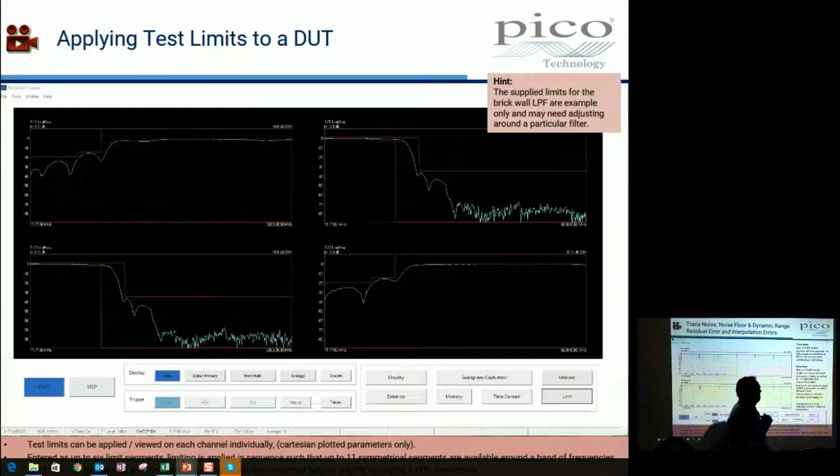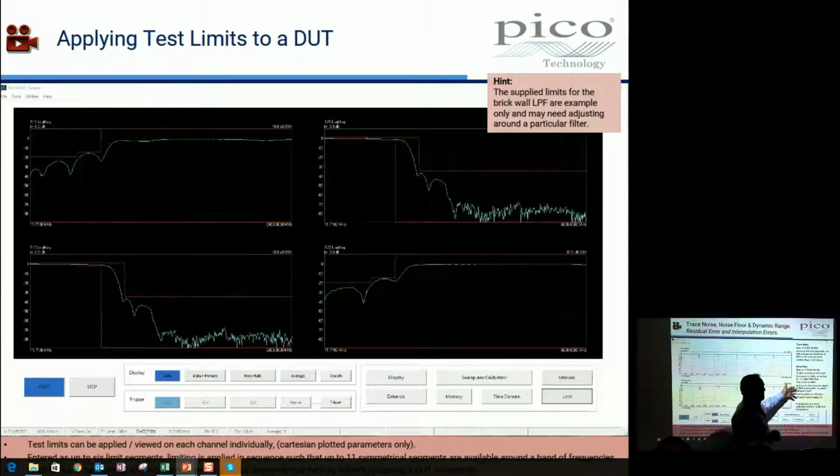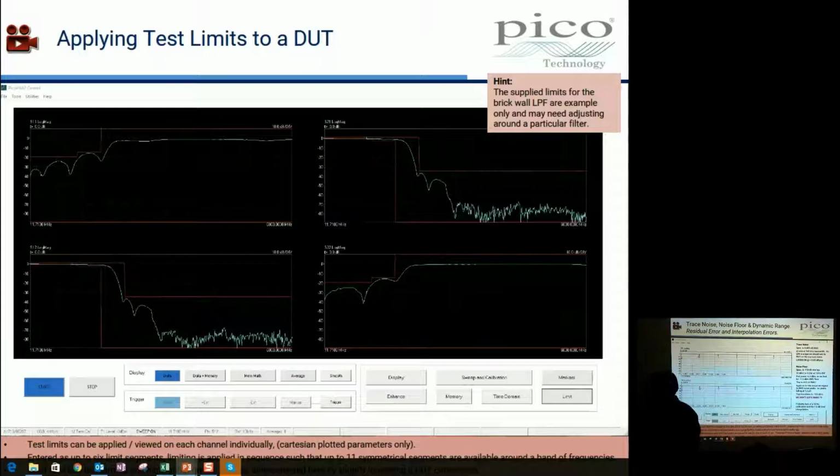Port power is 3 dBm. In the case of the test I'm going to do here, port power is 3 dBm. So we're going to be looking at minus 115 dBm RMS for our noise floor. That's what the spec says it should be. And that is 400 nanovolts RMS. That's pretty small, especially as we're looking at 4 gigahertz signals. We're expecting 3 times RMS noise peaks, so the peaks are going to be falling at around 1.2 microvolts, which translates to minus 105. As you'll see in this demo, we don't quite make it, but then we'll show you how to make it. But let's do this one first.